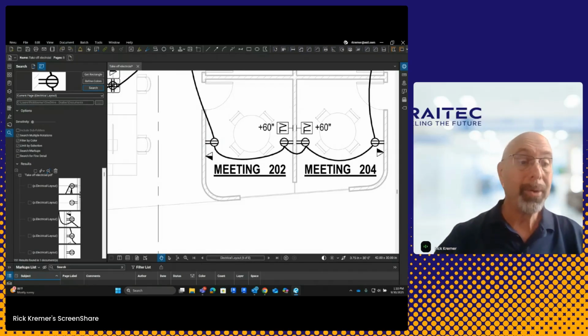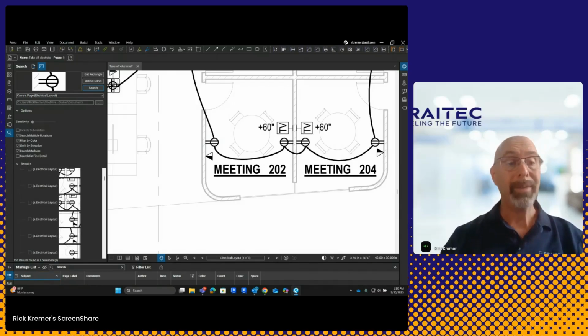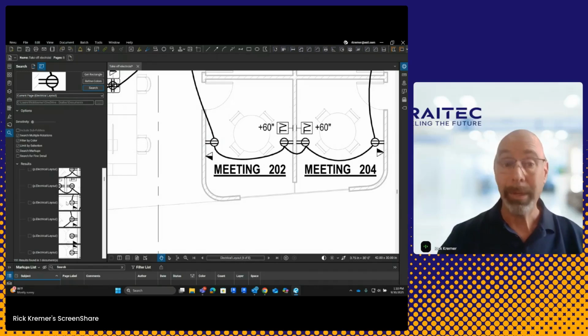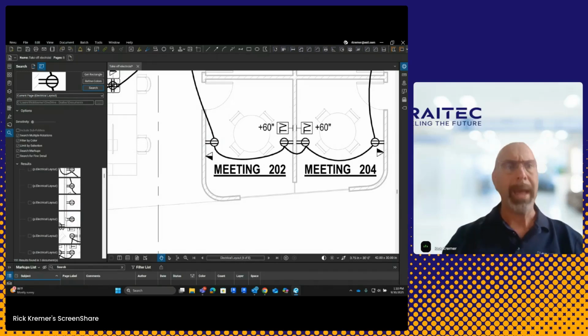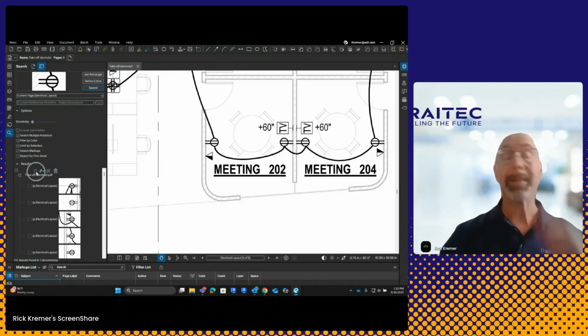Here in Bluebeam Review, on the results panel, you'll see a preview of everything that it picked, which it did a really good job. So you're going, well now what? Here, all I need to do is select the icon over here next to the lightning bolt to select everything that it previewed. I'll go ahead and click on it, and you'll notice that it goes through and places a check mark on all of these searched results.